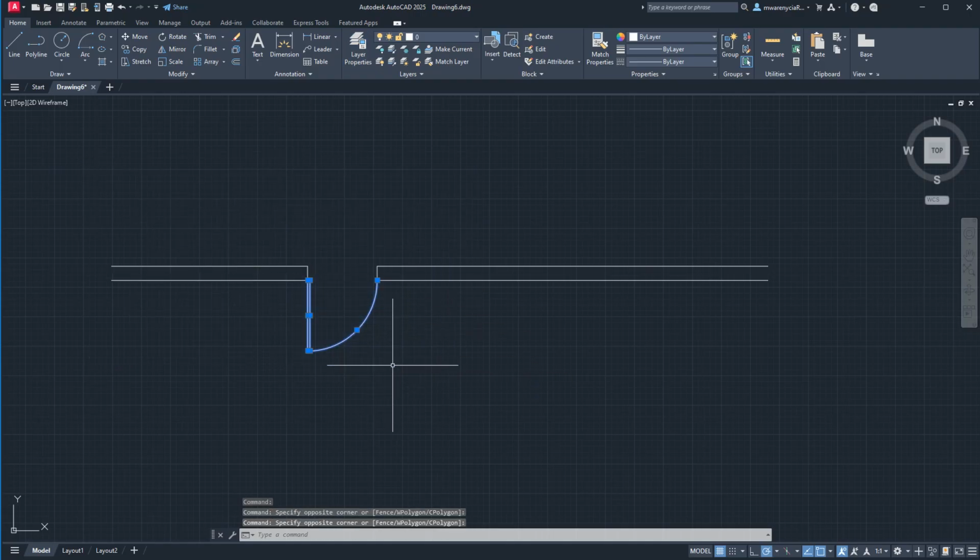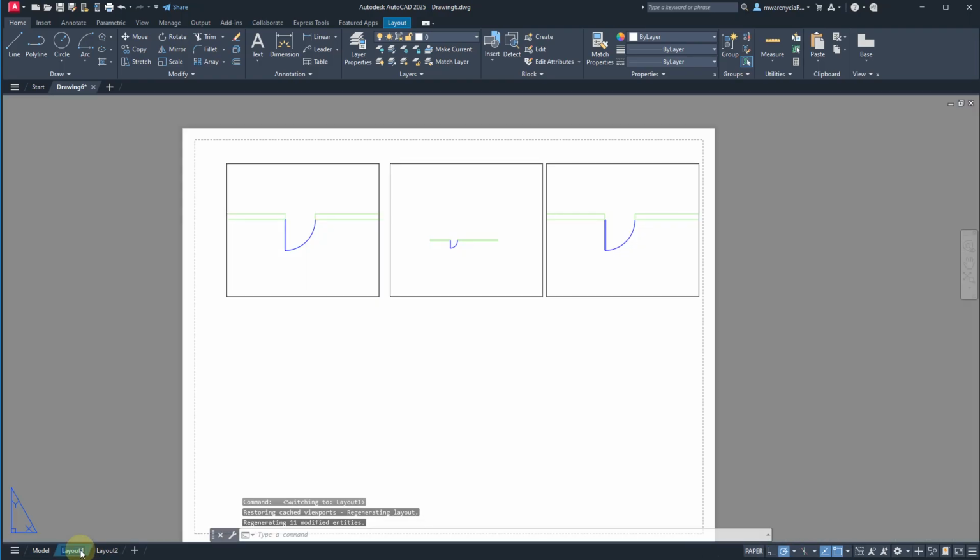So now this is my door. It's part of the doors layer, so I will move this to my doors. I don't know why that didn't assign that. Okay. So you can see now my walls are on my walls layer, my door is on my doors layer. There's a couple other things that I want to highlight with this.